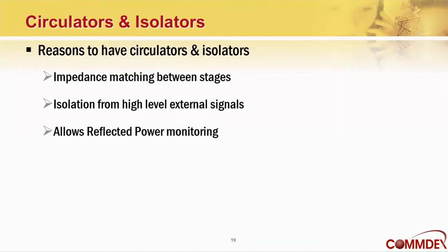And now we're going to talk about circulators and isolators. They're really two different flavors of the same thing. They're used to route the radio frequency traffic and isolate devices. They provide impedance matching. They isolate from high unwanted signals. They also allow the monitoring of reflected power.